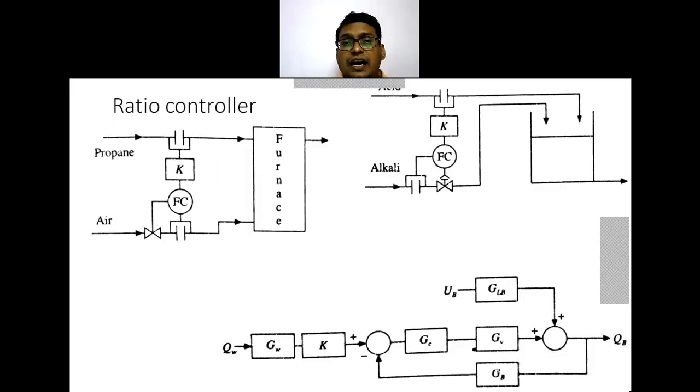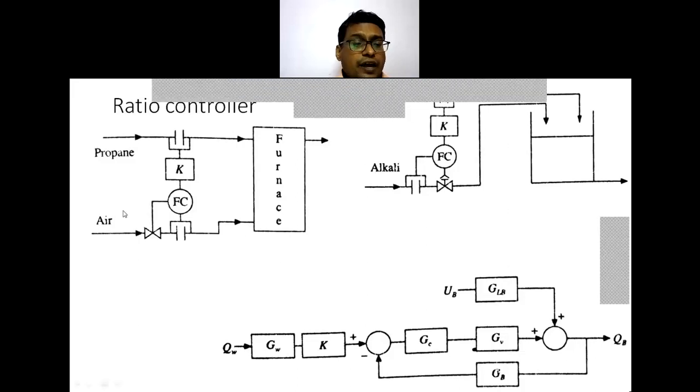Now we will see a system where propane is burned in the furnace, and to burn this propane you require air. So for example, we need 150 kgs of oxygen for say 40 kgs of propane to burn. A certain ratio is there. Based on this stoichiometric calculation, we will decide a certain ratio, how much air is required to completely burn this propane.